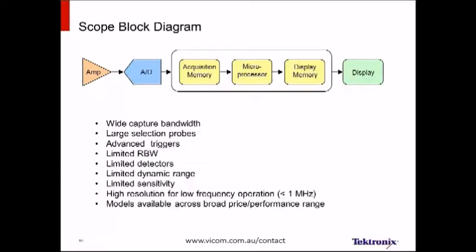When I think about sensitivity, oscilloscope sensitivity is in the millivolt range. Spectrum analyzer sensitivity is in the nanovolt range. So we're going to see a lot more detail with a spectrum analyzer versus using an oscilloscope.